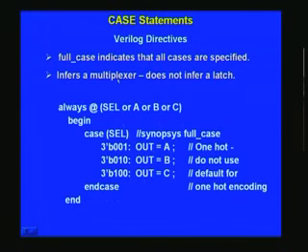how this does. So there is a directive called synopsys full case, full underscore case. This looks like a comment, but it is a directive. It is more than a comment, right? So take care that you don't put this as any of your comments. If you do, you will get into trouble, right? What all it signifies for the synthesis tool or even a compiler is that we have given only a partial list here. We have not given the entire thing, but you regard it as a full case. That's what the implication here is. So just by giving this here, you don't have to list all the conditions, right? Is it clear to you what a full case is?